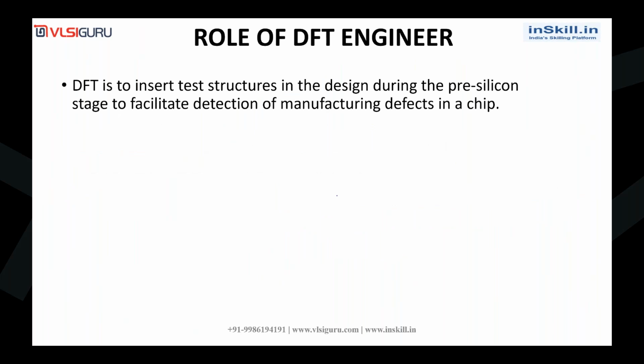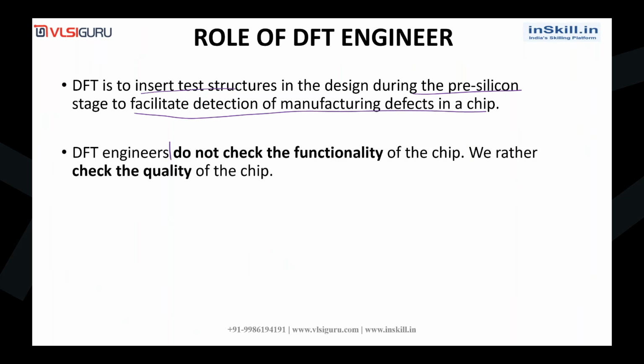Okay, so the role of a DFT engineer. DFT is to insert test structures in the design during the pre-silicon stage to facilitate the detection of manufacturing defects in the chip. Yes, it is the same point we discussed in the previous slide. DFT engineers do not check the functionality of the chip. We rather check the quality of the chip. So what does that mean? We will try to understand here.